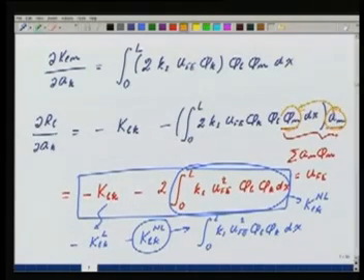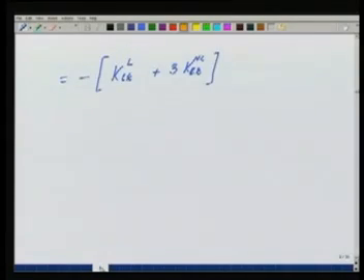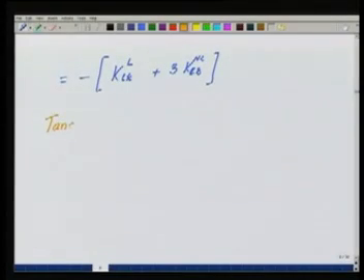Okay, so once I have this, now I have the representation. This matrix, because it came from the partial of the residue with respect to the solution vector at the current solution vector, is called the tangent stiffness matrix. So we have the tangent stiffness matrix, that is the local slope in the drawing that we have made in the beginning.